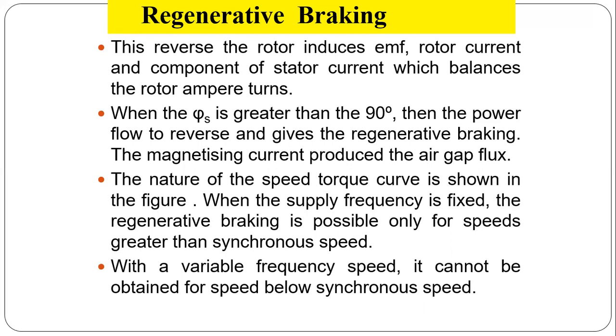The magnetizing current produces the air gap flux. The nature of the speed torque curve is shown in the next slide. When the supply frequency is fixed, regenerative braking is possible only for speeds greater than the synchronous speed. This is the main limitation of regenerative braking of the induction motor drive. With variable frequency, it cannot be obtained for a speed below synchronous speed.